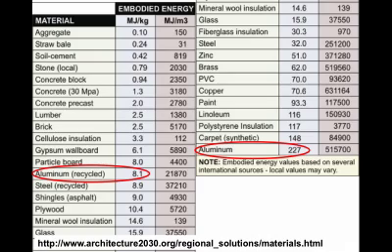However, if you're trying to find out the life cycle energy input of a product you're making, if you make it out of aluminum, you can't say, oh, I'm going to make it out of recycled aluminum because that will have lower embodied energy. It's kind of like marginal electricity. When you start to buy more aluminum, people are already recycling as much aluminum as they can. So the extra aluminum for your production is going to come from mining, and your product is going to bear the full 227 megajoules per kilogram of embodied energy.